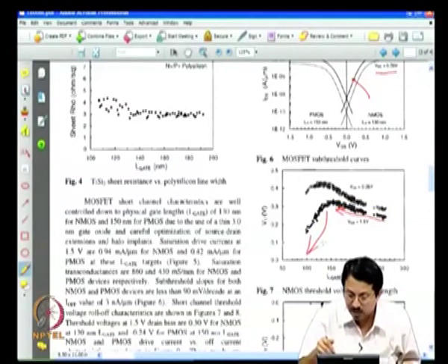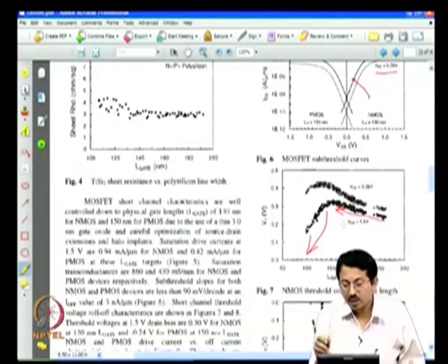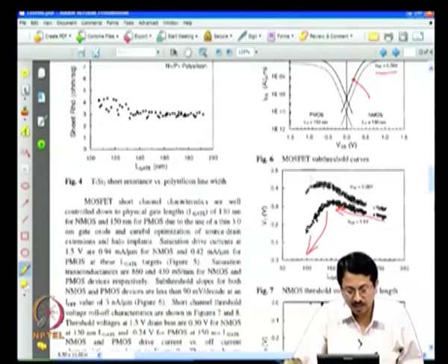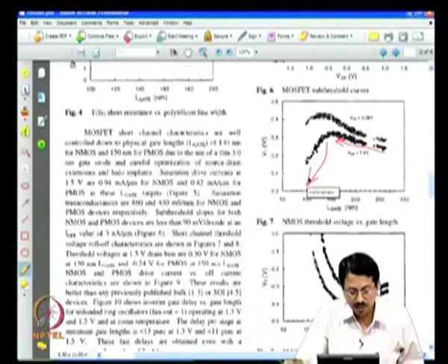This region here VT is coming down. This is VT measured at 1.5 volt on the drain, and this is VT measured at 0.05 volt on the drain, and this difference is essentially your DIBL, right. VT at low voltage on the drain is always higher than VT at high voltage on the drain, right. Your DIBL can be characterized based on that. Okay.